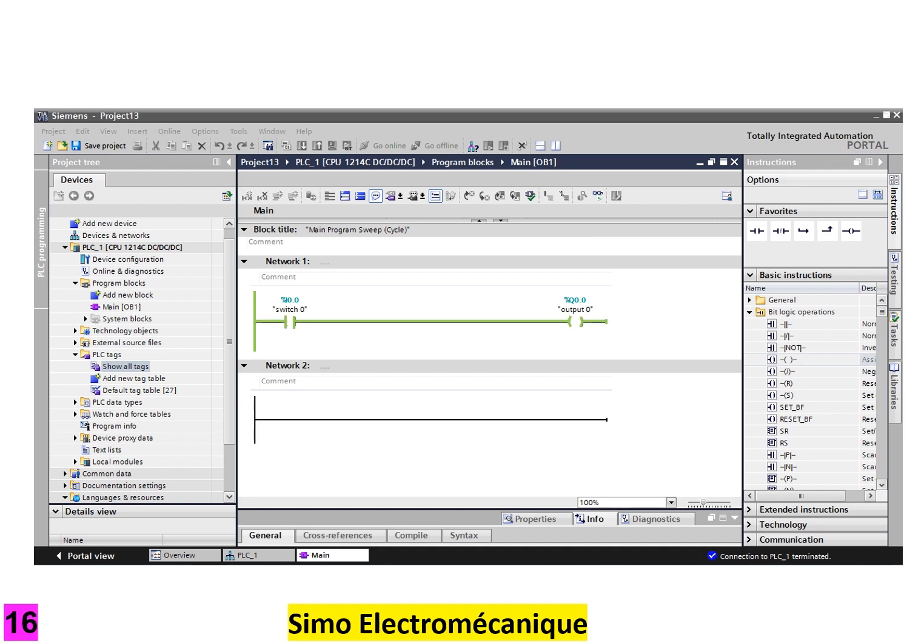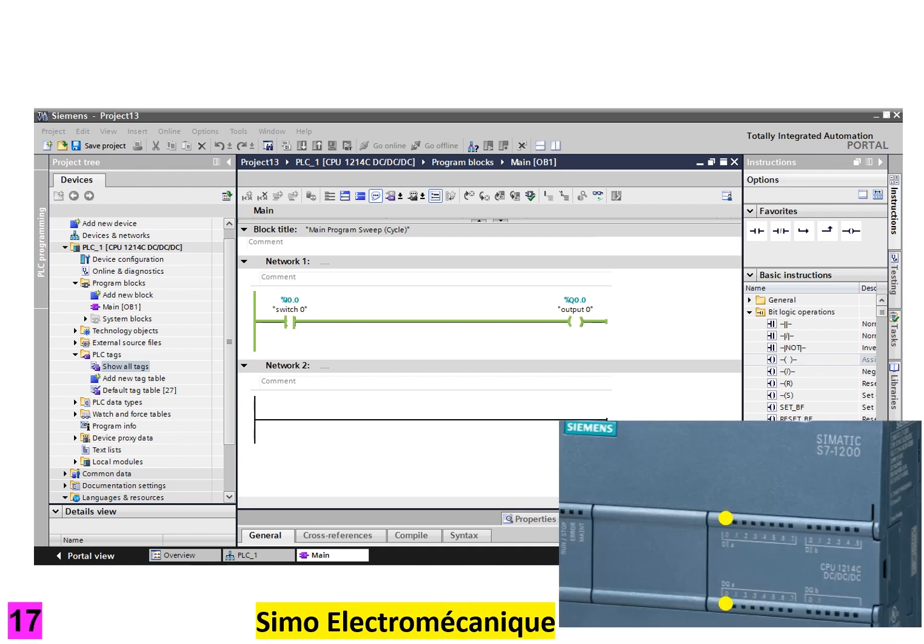And because the output is a normally open output, if it sees a logical 1 or the presence of current on its input, it will switch on. We can toggle the input switch to see the effects in real time. Look at the inputs and outputs and you will see that output 0 will follow the state of input 0. Look at the inputs and outputs on the front of the PLC and you will see that output 0 will follow the state of input 0.